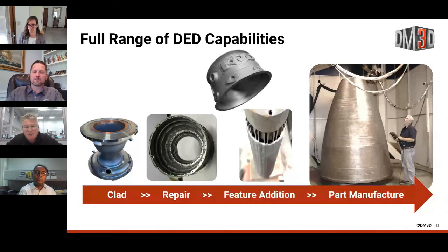But there's another fundamental to think about here also, and that is that you would have to keep the monitoring system, the inspection system, completely separate from the machine itself. The reason for that is that if you mount the monitor on the same head as the deposition, and say the axes of the machine are wrong, you'll be depositing wrong, but your monitor will say that it's right because it's on the same skewed axis.